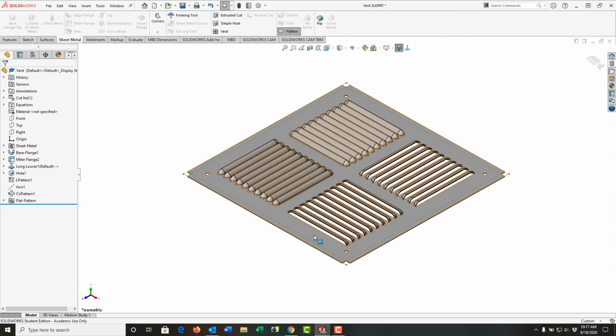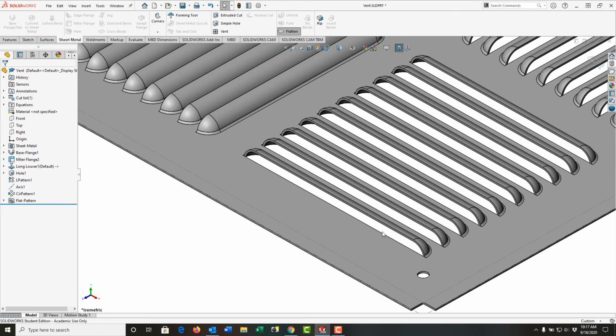And remember, these are done with the forming tool. And when we bring the punch press down and punch these out, the material will cut or rip itself here to form this from the material that was at this location.